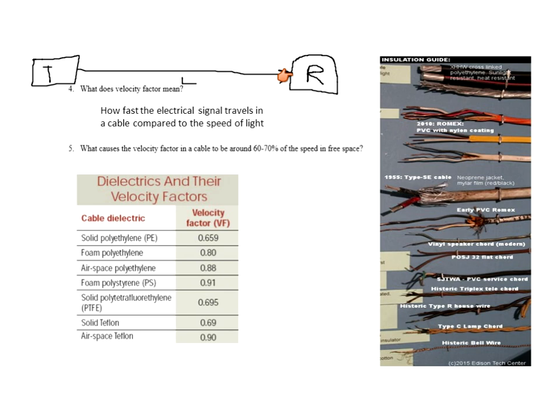Now, the comparison of how fast the wave travels in that line compared to free space is called the velocity factor. So, some cables have a very high velocity factor, which is very good, and those ones typically have a lot of air bubbles inside of them. The insulation is made out of air bubbles. Some of them have a pretty slow velocity factor. They run pretty slow compared to the speed of light or a radio wave in free space. Those ones are typically solid plastic for their insulator.